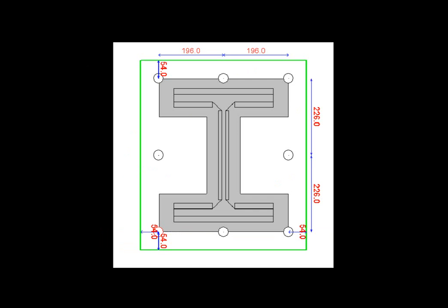If the plate is too thin, then it will be bent excessively and will not be able to bear the load. In this example, the welds are considered as clamps, magenta-colored dots. We can now see what would have happened if the bearing surface had been a smaller surface, consisting of the applied load footprint with a border added around it, as illustrated.